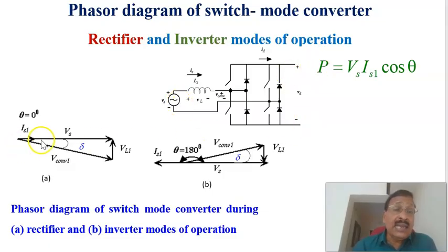source. And in that case, if this corresponds to the rectifier mode of operation, so if you make the converter 1 voltage with this much magnitude and this phase angle here, of course the converter 1 voltage plus VL1 equals the grid voltage Vs. So this is the VL1. Always, as I already explained, the current through the inductor is 90 degrees lagging the voltage. Therefore, this is the current through the inductor Is1. The fundamental current from the source, that is the Is1 vector, is this one, and this is the VL1.